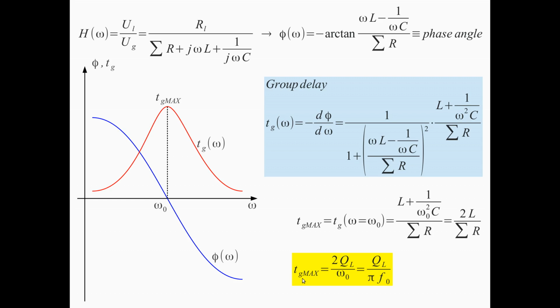The maximum group delay of the tuned circuit is defined by its Q loaded divided by pi divided by the central frequency. I make this derivation at omega 0, at the central frequency, because for my filter with a single tuned circuit, the group delay is the largest there. In other filter designs, the group delay may be larger in some other regions, not at the central frequency.